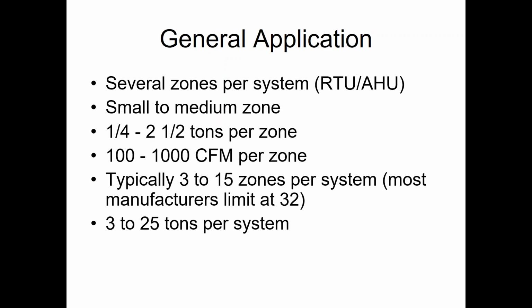So once you start getting above 20 zones, I know I have on here 25 tons. Once you get above about 20 tons, I'm probably going to raise a red flag and say, what are you doing, man? We got to look at your building. Something's probably not right here. And even now, I used to say 25 tons when I made these slides 15 years ago, and today I'm telling you 20. And if I went and talked to Sal or one of those guys in my office, once you start getting to like 15 tons, they're probably thinking like a mini VAV system, because that's possible now with some of the equipment that we have.